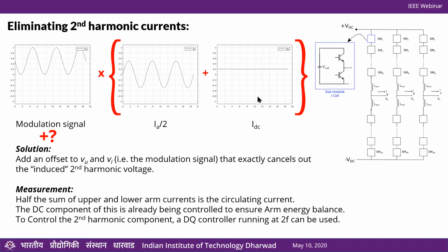Second thing is, we've talked about MMCs in grid connected applications where the output fundamental frequency is nearly fixed. There's no case where your output voltage needs to be at lower frequency, whereas in motor drives you may have to operate at very low frequency, right? Researchers have looked at using MMCs for motor drives, but it is significantly more challenging because as frequency goes down, for the same ripple value, you need larger and larger capacitors. So that's one challenge. People are looking at it.